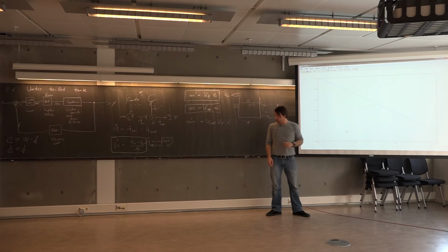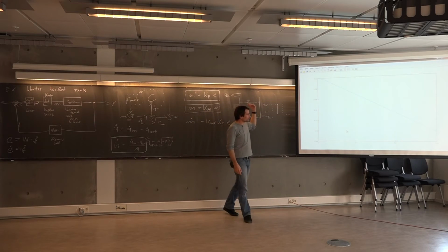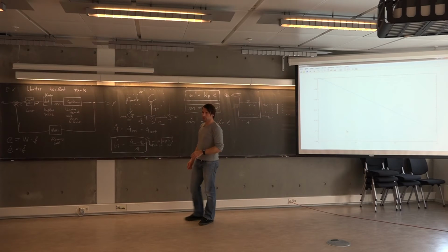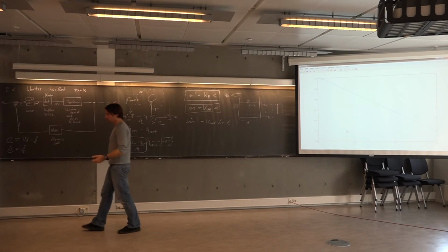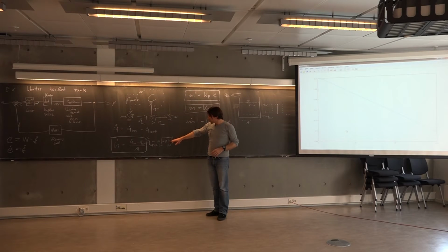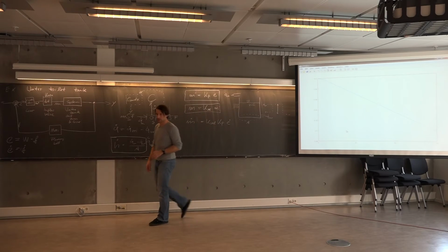It's due to our very simple and crude model which we have used here. It's basically a linear change in water height over time, which is not correct physically, obviously, because this is highly nonlinear. If the height changes, the outflow will change in a nonlinear manner.